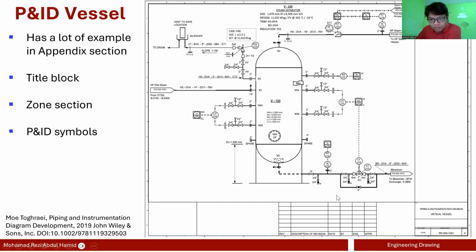So that one is done. This one also done, and then the other one here is we have a pressure transmitter connected to a 2-inch nozzle, gate valve 3/4 inch, 3/4 inch, and then you have a pressure indicator transmitter to indicate the pressure. Because it's mounted on the unit, it indicates the pressure, and at the same time it will transmit the pressure information electrically to a pressure indicator at the DCS, also equipped with high and low pressure alarms.